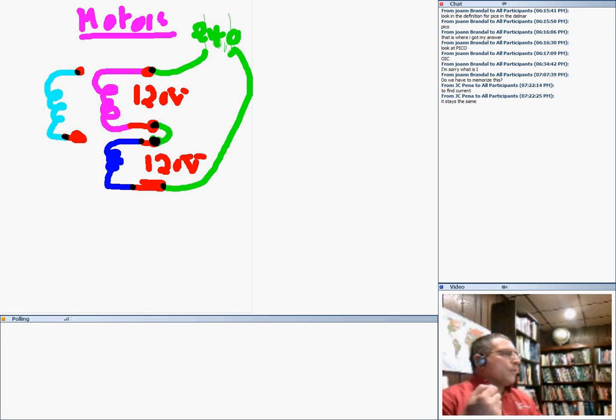That's what we do in motors, guys. We put the two coils in series. Can you guys see the two coils in series? Everyone can see that the current, the two are in series now, right? Now I can series the coils to get me a higher voltage. Each one of them is rated for 120. Together, they make 240. So now I can tie them to a 240 system. Now this motor can run at 240.